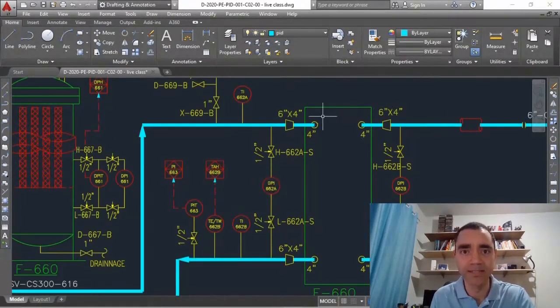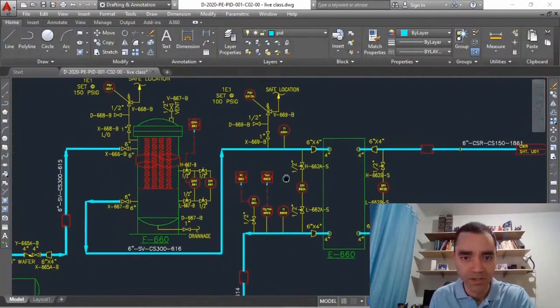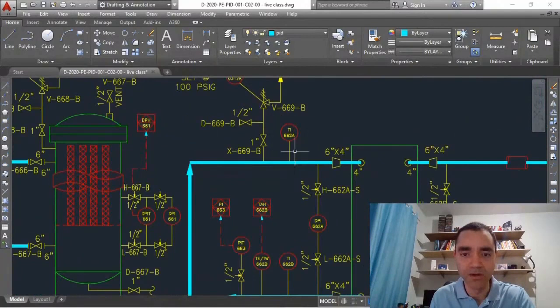We are using a plate exchanger, and it is very sensitive to dirt, and if we have dirt we will have less heat exchange area, and we can evaluate based on the pressure differential if we need to clean the equipment or not.